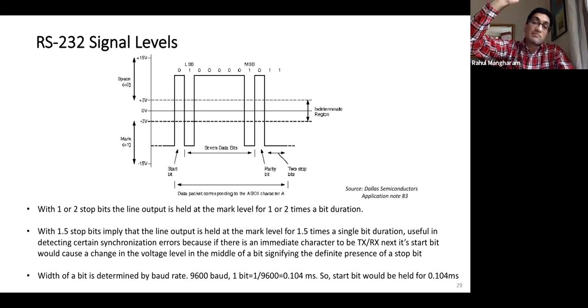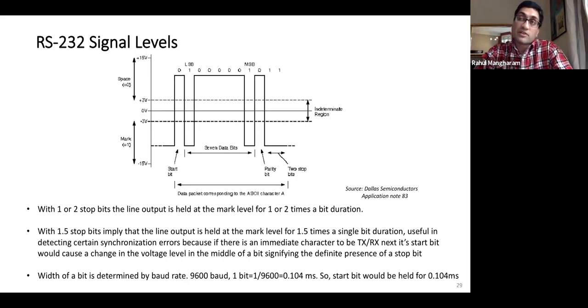And it's saying, okay, here's the 8th, the 9th bit that you get is a parity bit. The 10th and 11th bit that you get are basically just saying, stop, this is the end of the packet, like that, right? So it's just a way of communicating that this packet is kind of self-contained. Every time you get this, you have the same format and the data is within that format. So hopefully that answered a little bit about parity bits, maybe a little bit more than you asked for. But we'll cover that again next week with wireless communication.